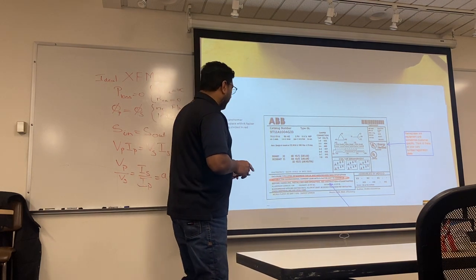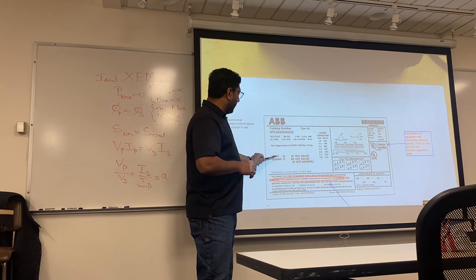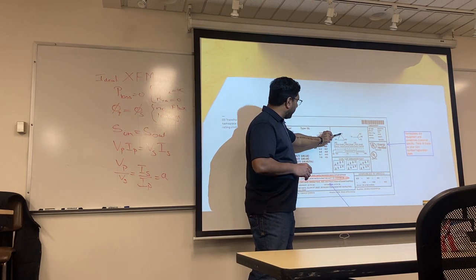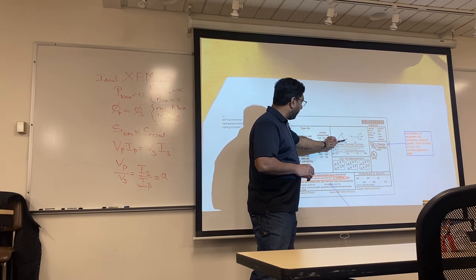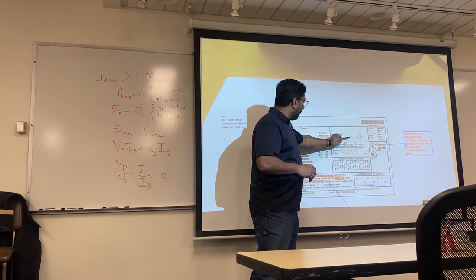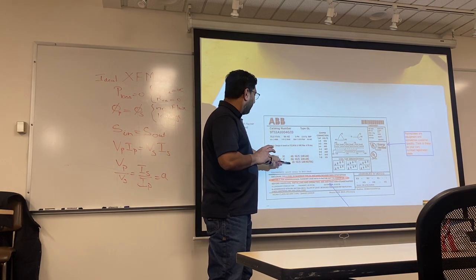The primary is stuck at 480 volts, and that's because it's a delta, so if you take a voltmeter here, between H2 and H3, it's going to be 480. On the secondary, you get a choice of two voltages. You either get a 208 or a 120.